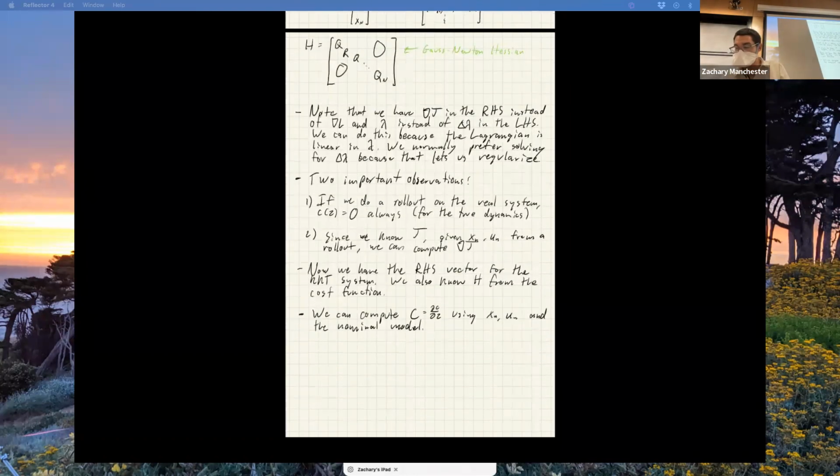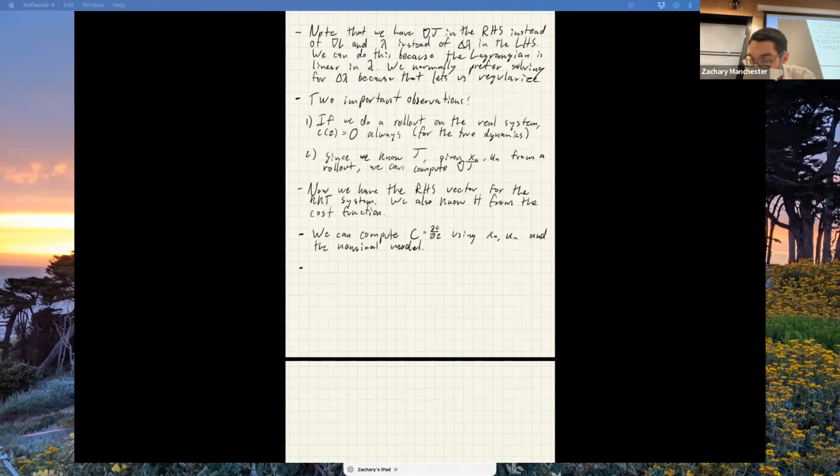So you could do that, and that can work perfectly well. If you were to try to do trajectory optimization from scratch on the real hardware, you'd probably do that, and that can work. Instead, what is maybe more common is a sort of offline, online, sim-to-real transfer type of thing, where offline we optimize the trajectory using just the nominal model, using standard trajectory optimization. And what we really want is for the real system to perfectly execute that task, track that trajectory.